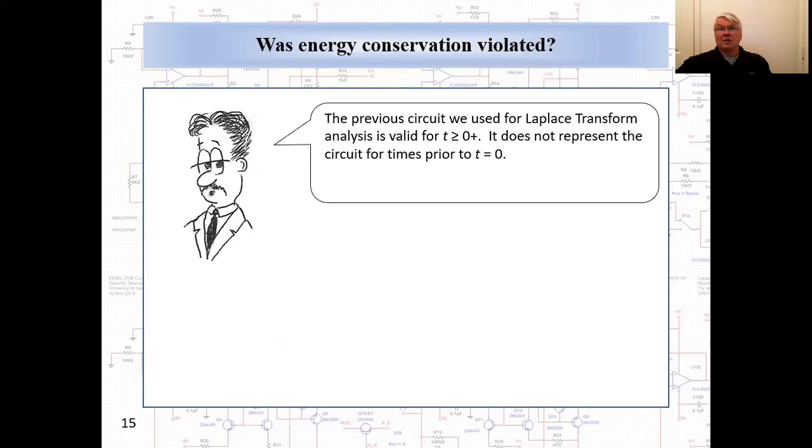Was energy conservation somehow violated? Well, one thing I will note here. The previous circuit that we used for the Laplace transform analysis is valid for t greater than or equal to 0 plus. It does not represent the circuit for times prior to t equals 0. So we can't look at the behavior of the circuit across the transition with the Laplace analysis.